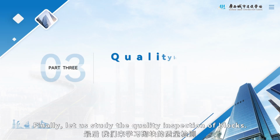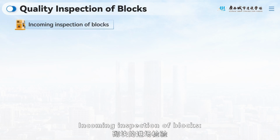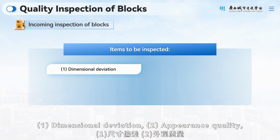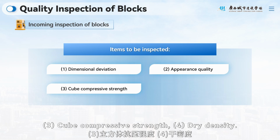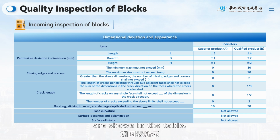Finally, let us study the quality inspection of blocks. Incoming inspection of blocks. Items to be inspected include 1. Dimensional deviation, 2. Appearance quality, 3. Cube compressive strength, 4. Dry density. Dimensional deviation and appearance requirements are shown in the table.